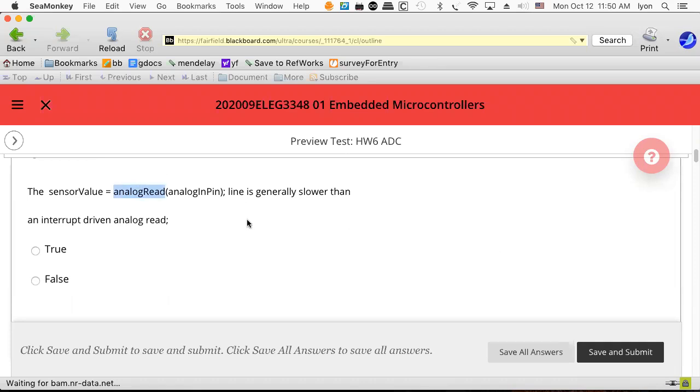In fact, the default rate on that is 9.6 kilohertz. It's all using the same underlying hardware that we were directly manipulating before with the bit manipulations. So it doesn't have any inherent disadvantage or advantage, but having something that's interrupt driven has an inherent advantage, because now you can have other things running in the background, like printing.